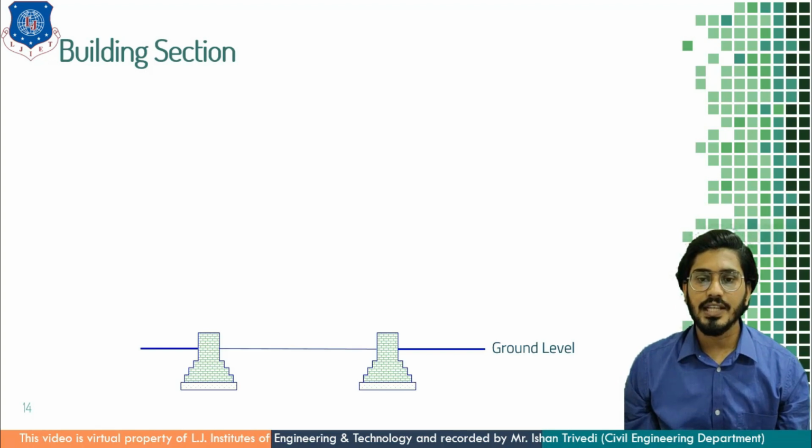First, we have seen the foundation as a part of substructure. If a wall thickness is 30 cm, then the base of the foundation is 90 cm or 0.9 meter, and step footing will be provided consecutively in 3 layers having widths of 60, 50 and 40 cm. Once you reach ground level, a plinth level has been provided.